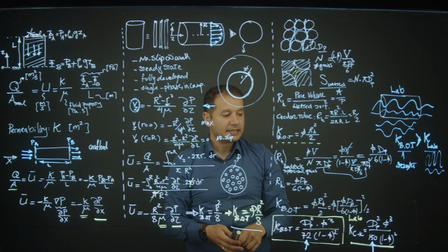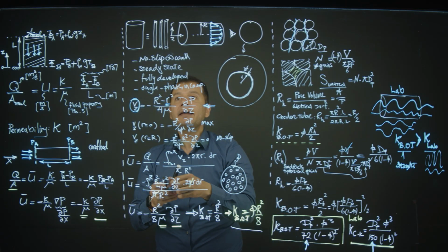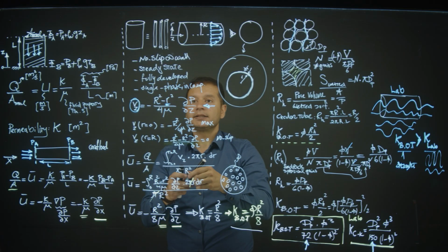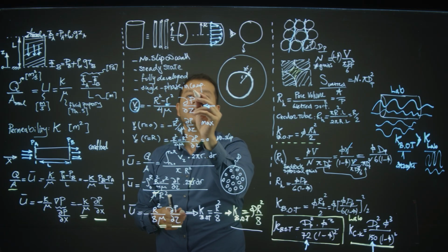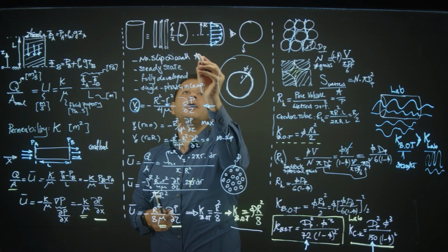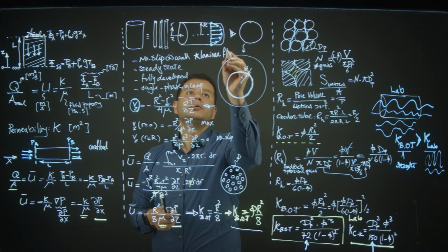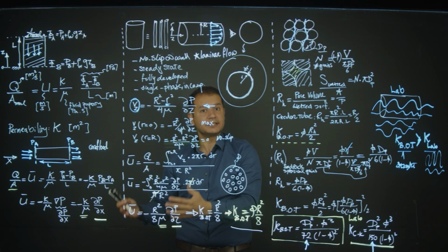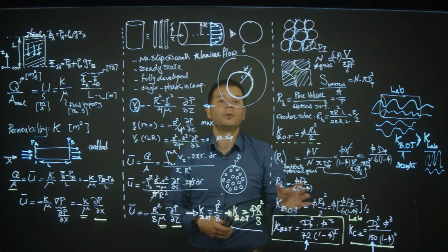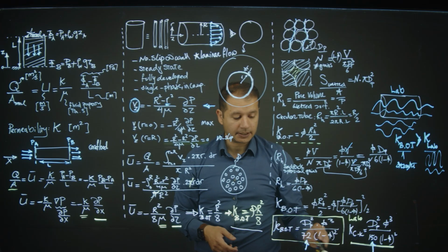What we will do next is go towards a more fundamental understanding of what it means to have laminar flow as one of the main assumptions of Darcy flow. So I said no slip wall condition, a steady state, fully developed boundary layer, single phase, incompressible, and above all laminar flow. And if the flow is a bit faster than the pure laminar system, there will be corrections and additions to Darcy's law due to Forchheimer corrections, which comes in the next lecture.